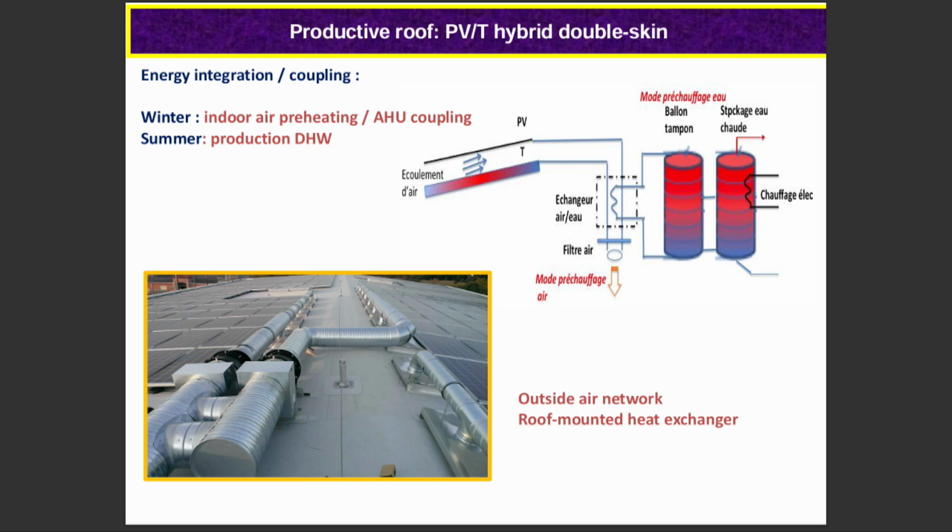So we had in this design a heat exchanger, which is not so common, between air and water. Usually it is the other way: you use hot water and exchange on the air. Here it was to use the air and exchange on the water. So it's not so good in terms of heat capacity of air, but the quantity of air was massive. And thanks to that, we produce hot water during summertime that could be used for cleaning.